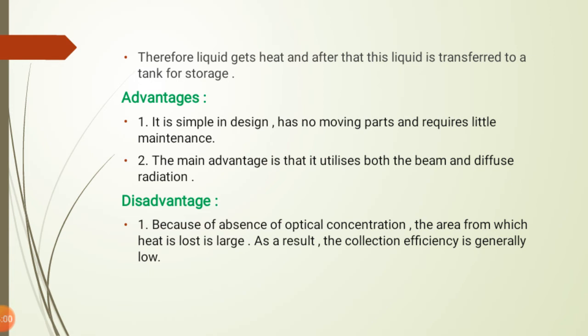The second main advantage is that it utilizes both the beam and the diffuse radiation. As we have seen before, the liquid flat plate collector utilizes both the beam as well as the diffuse radiation, so it has maximum efficiency, or the ability to produce a maximum amount of heated water, or hot water.